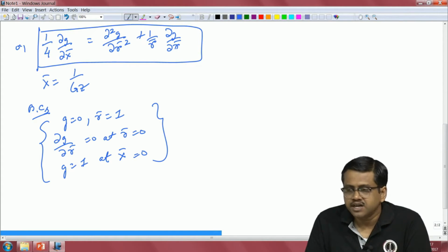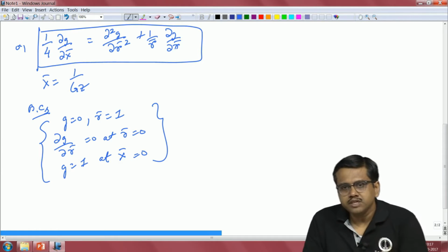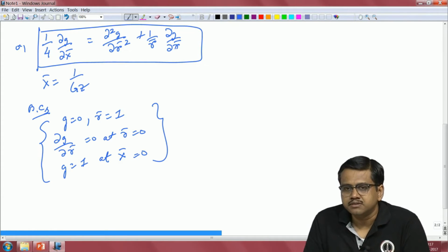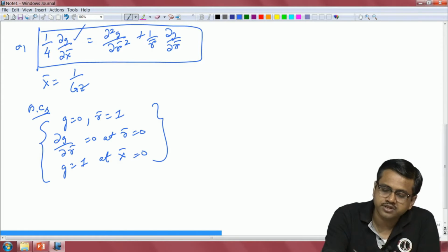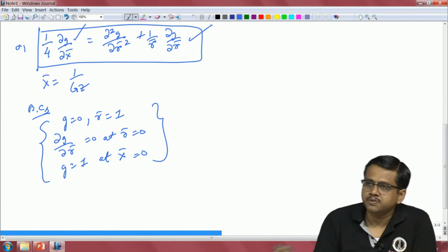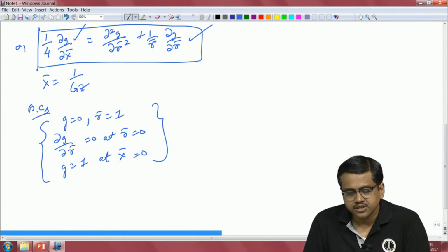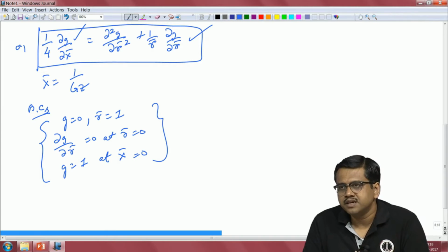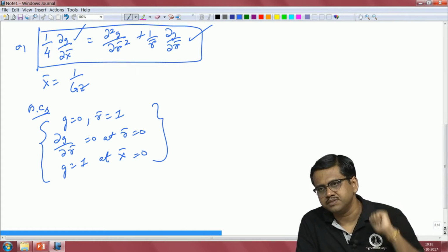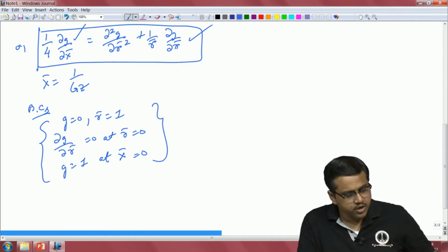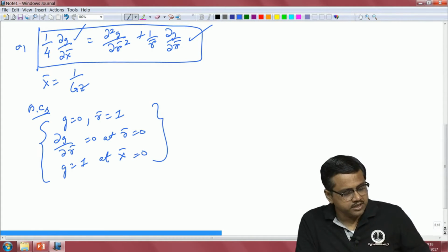In a 1D transient heat conduction equation in cylindrical coordinates, one term will be your time and the other will be the corresponding spatial coordinate. Here, x bar is doubling up as your time, so the axial length is what your time scale is all about. So it is very equivalent, though the problem is not the same.